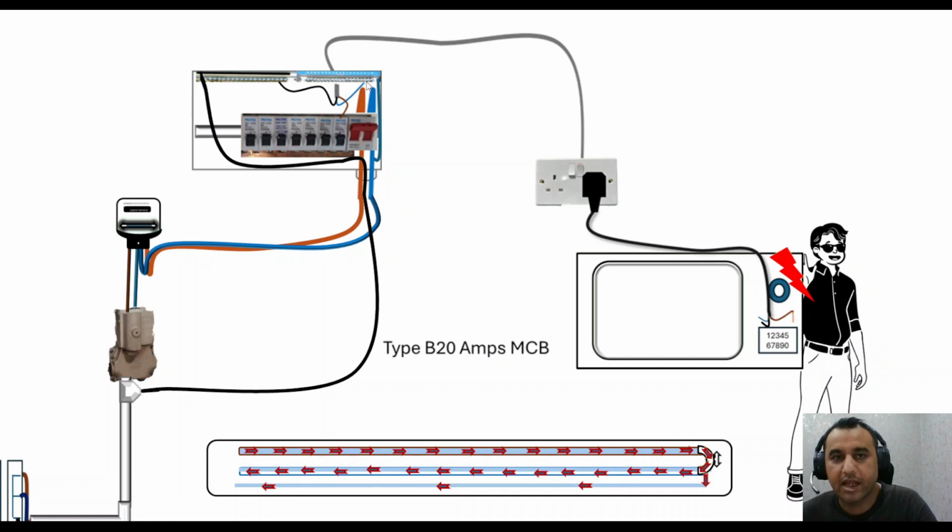In this case, we probably haven't got an overload or overcurrent, because if you're getting 8.69 amps coming to this microwave via this line conductor, and it's going back 7.69, so we've got 1 amp flowing here, which is fatal, enough to kill anyone who comes in contact with the live part of the appliance.